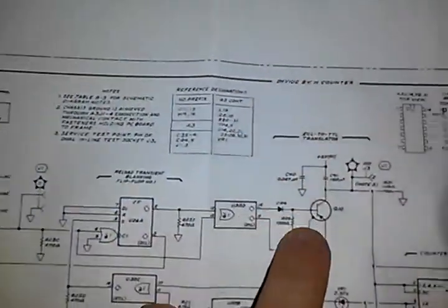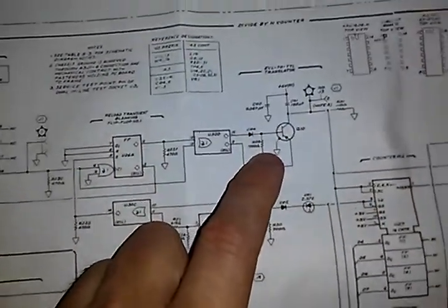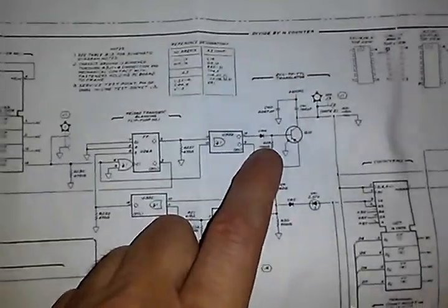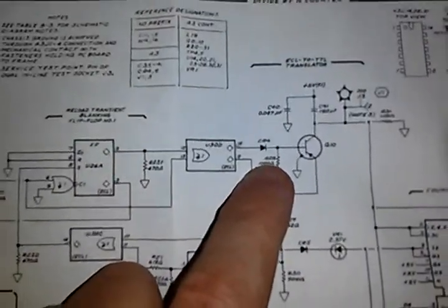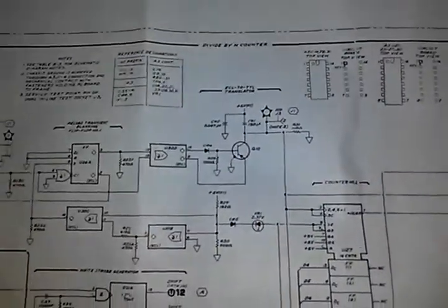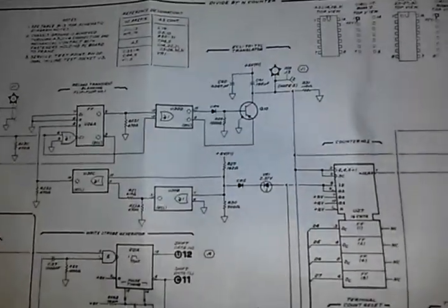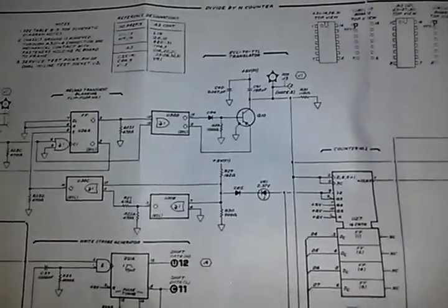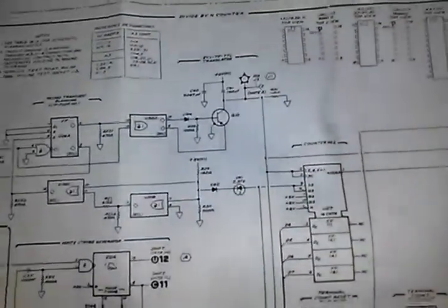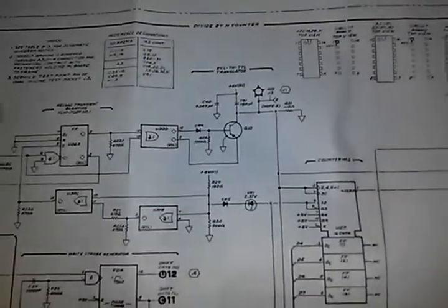Originally, I thought something was wrong with this level changer here. This basically, as I said prior, changes the ECL logic to TTL. Again, in the previous video, if you take a look, you'll see that under certain conditions, it was losing, either it wasn't the proper ECL, the proper TTL levels were not being obtained.